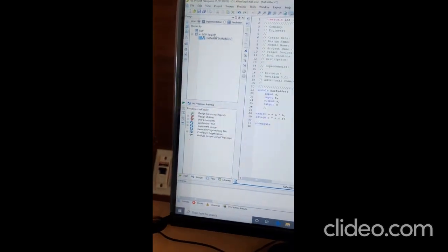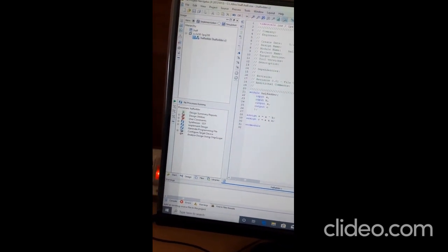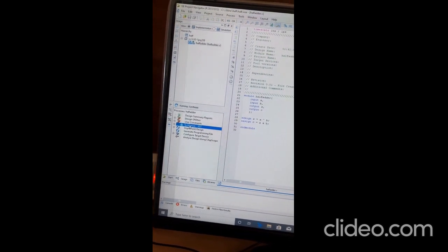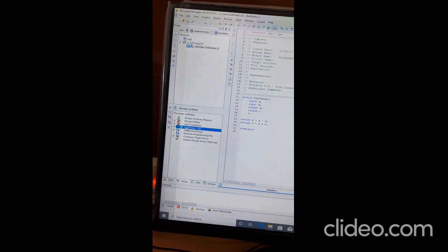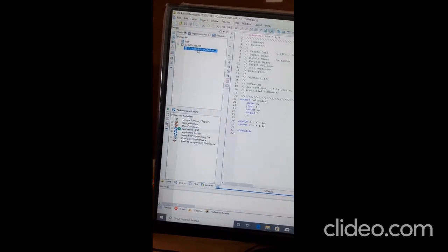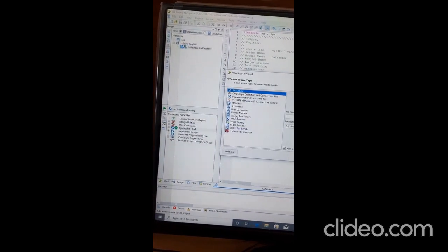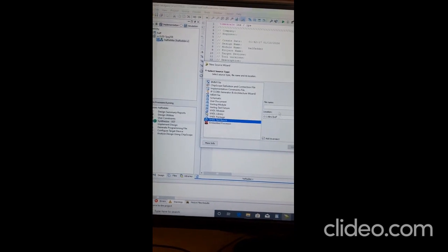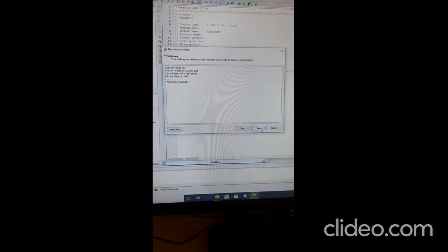Next, the procedure to be followed is right click on this. Okay, first save this, double click on synthesis, then after getting a green tick, right click on half adder, new source, select VHDL test bench, give the name for the test bench, next, next, finish.